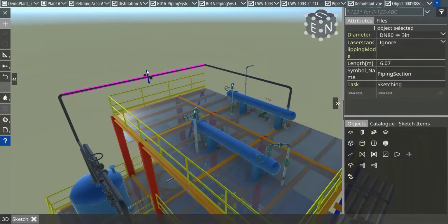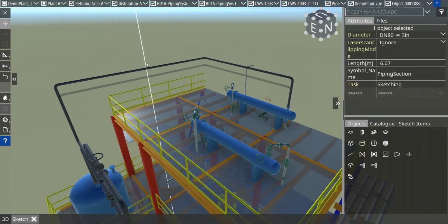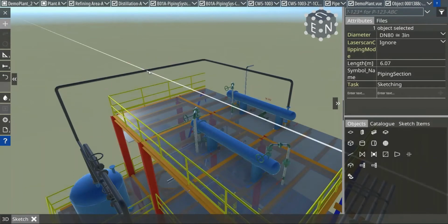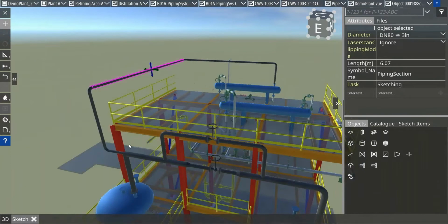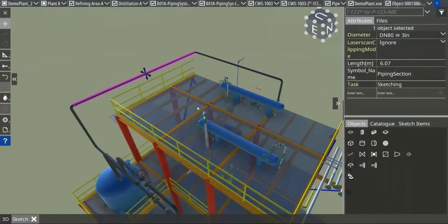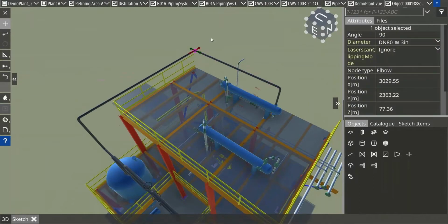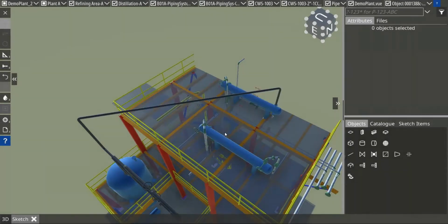Here, my single legs or my single pipe runs can be changed. You see how this is working. It's working in an intelligent way, and quite obvious, quite easy. You instantly see how this is working. When we look at this element, for example, and I delete this node here, you see the pipeline is like a rubber band. Okay, so I have deleted one node in between, and so this element goes straight now.